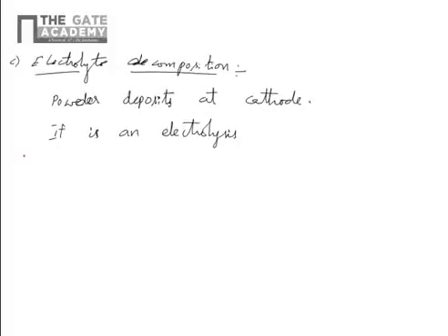We are not entirely discussing the whole process, because it's electrolysis, we know that anode and cathode will be there. You can keep both anode and cathode as a metal piece, or you can keep only the anode as a metal piece, because most of the material ions pass from anode to cathode compared to cathode to anode. So if you want to create metal powder of steel, keep the steel rod as an anode, and you can keep a steel rod as cathode also to get more metal powder.